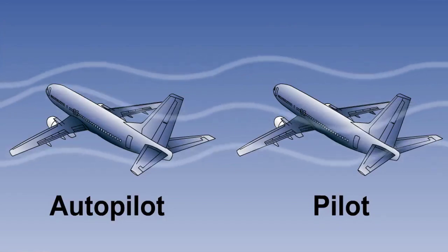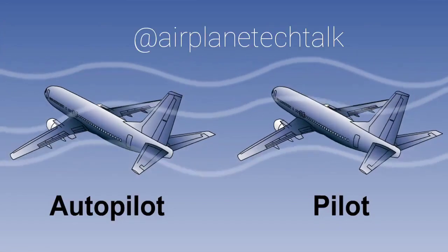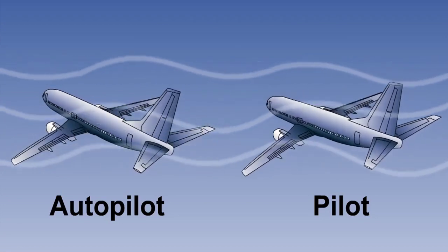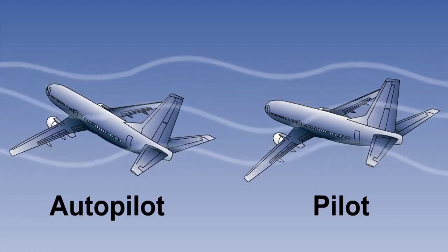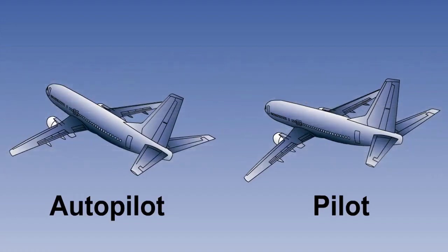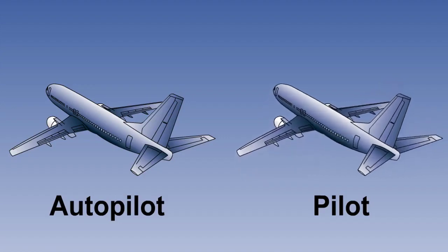The autopilot will react more quickly to a disturbance, therefore making the aeroplane more comfortable to fly in, and allowing more accurate maintenance of heading and altitude. It takes a pilot a certain length of time to react to a disturbance, and then still further time to decide which control to move and in which direction, whereas an autopilot has corrected the disturbance in a fraction of the time taken by the pilot to react.